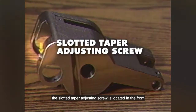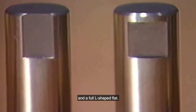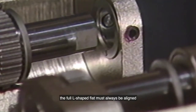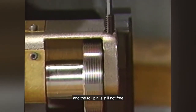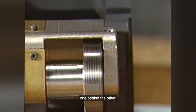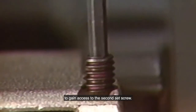For Type B, the slotted taper adjusting screw is located in the front, and the locking set screw is located on the inside of the roll arm. All roll pins are supplied with a partial U-shaped retention flat and a full L-shaped flat. In order to install the roll pin, the full L-shaped flat must always be aligned with the taper adjusting set screw. If you have Type A and have loosened the outside set screw and the roll pin is still not free, your thread rolling attachment may have two set screws, one behind the other. If this is the case, remove the first set screw completely to gain access to the second set screw.